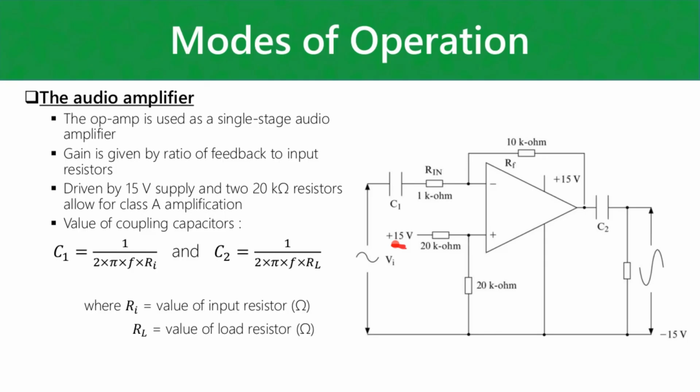But the thing is, usually this op amp is going to output to something like a transistor that's driving a speaker. And that transistor is going to need a positive bias voltage. You can't bias a transistor with a negative voltage unless it's a PNP transistor, but usually NPN transistors are used. So you can then use a single transistor to drive a speaker instead of using two transistors.